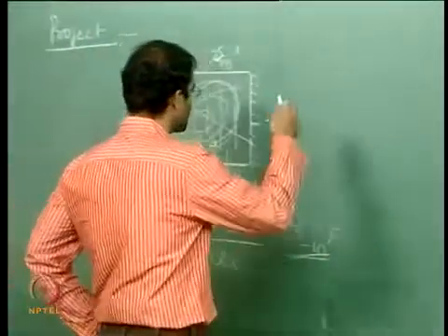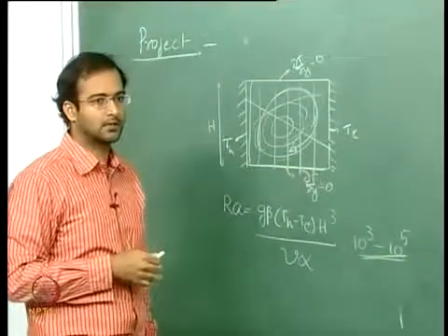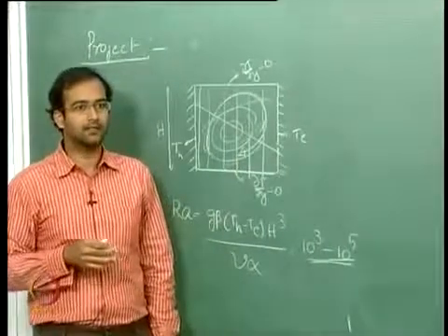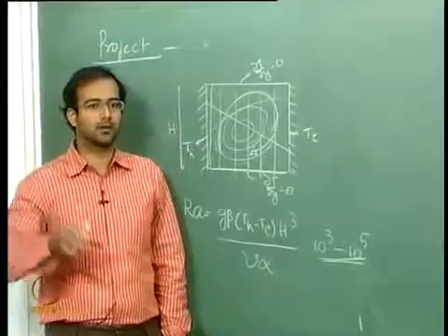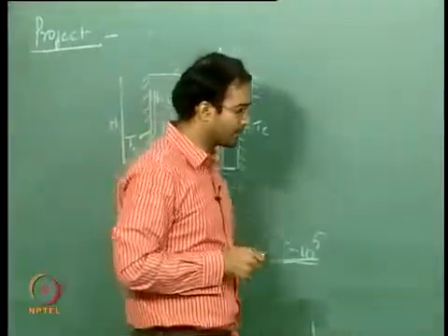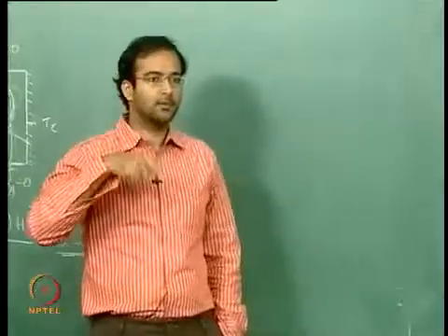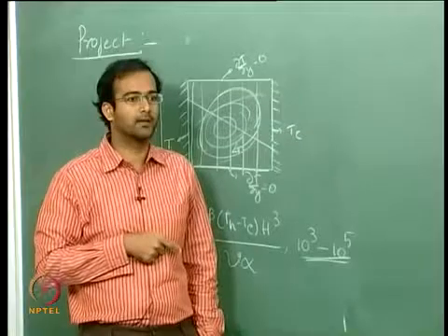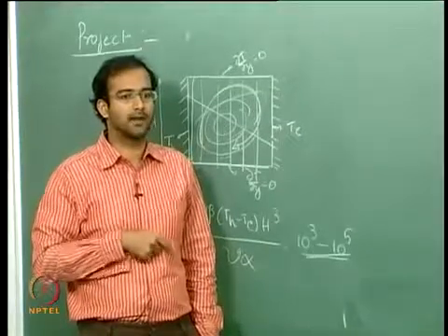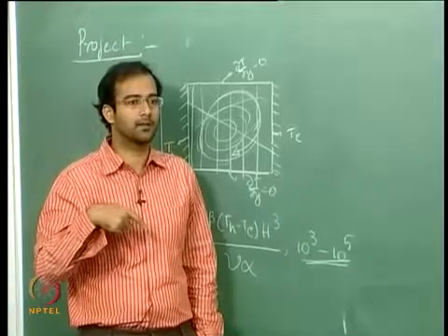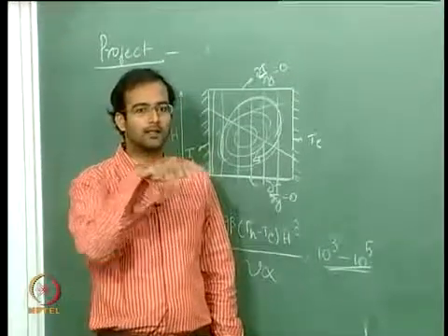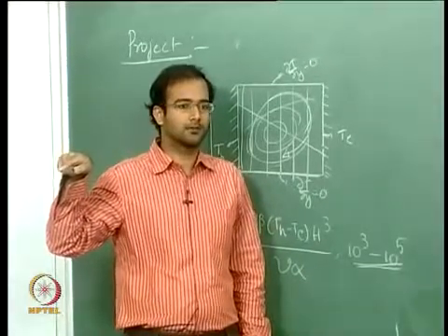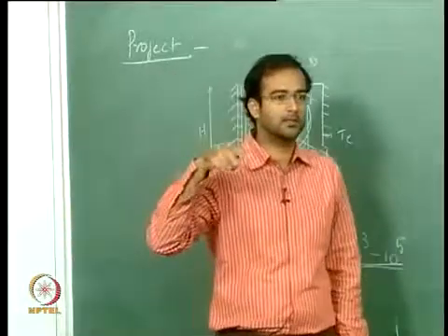Just to give you an overview of how the equations look for the case of natural convection. If you introduce the stream function, the advantage is that continuity is automatically satisfied, so you don't have to solve the continuity equation. Now you can eliminate the two momentum equations by differentiating the x momentum with respect to y and the y momentum with respect to x, and subtracting the two. Therefore you eliminate the pressure gradients and finally get a single equation devoid of pressure. So you have one variable less to solve, and the number of equations also comes down.